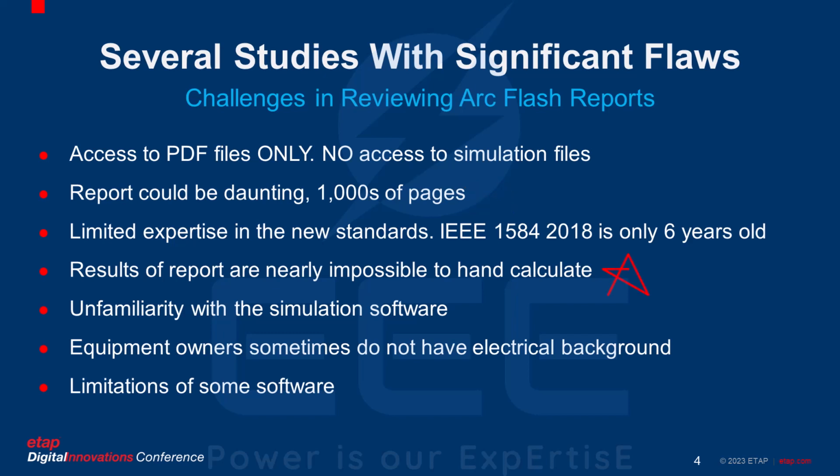3. Arc Flash key outputs are nearly impossible to hand calculate. Unlike short circuit current, load flow voltages, and few other data that can be hand calculated, it is almost impossible to hand calculate the calories or Arc Flash boundaries.